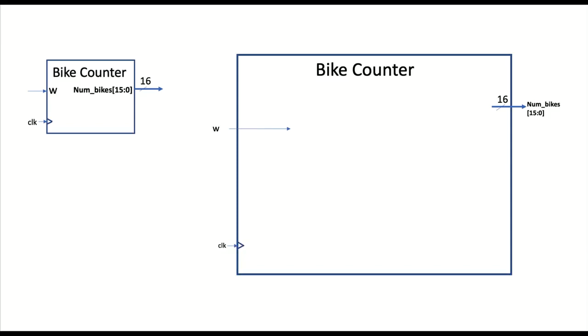Oh, okay. And what kind of device increments? A counter. Okay, so you want to have some signal which will go high whenever we see the pattern, and we will use that as, say, the increment or the count enable of a counter. Okay. All right, so we have one of those. Okay, so now I have to generate this signal that's going to go high for one clock cycle every time we see the pattern that looks like a bike.